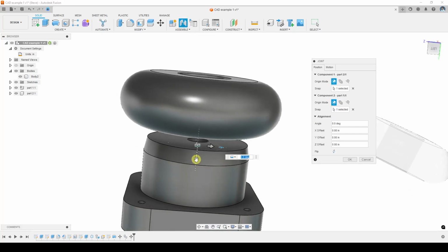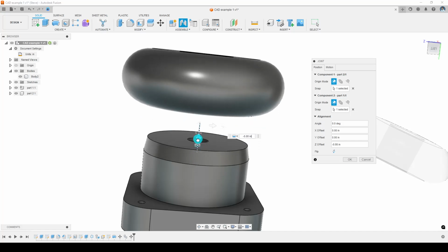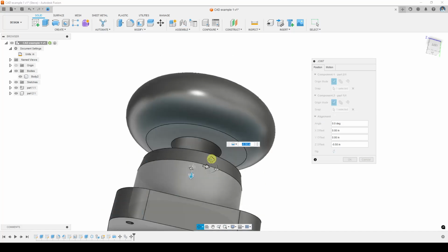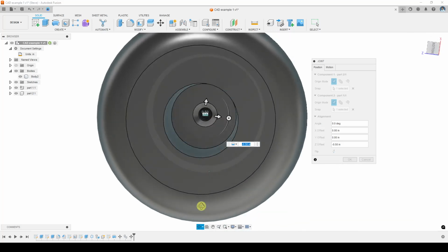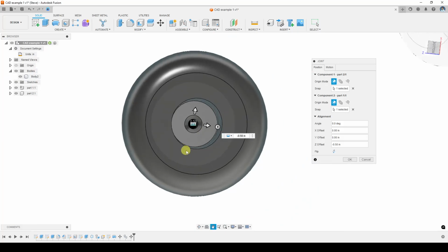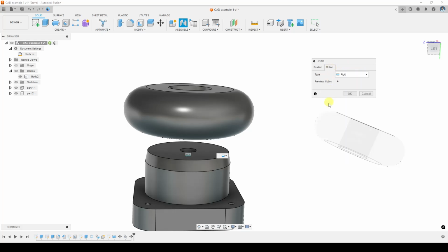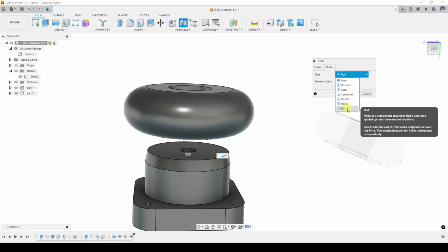And you can either pull it in to a different distance away. But now the axis of those two separate cylinders are aligned again. One more thing that we're going to set here is the motion. In the motion section, we could set all these different types of motion.